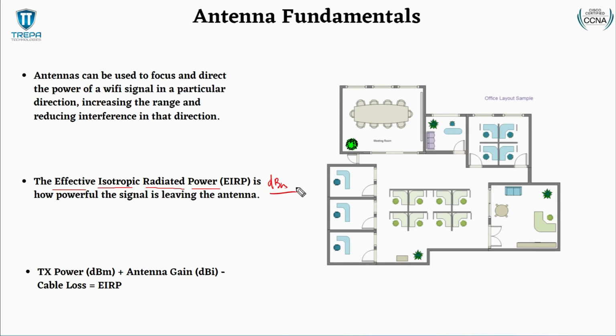So every antenna has a different EIRP rating. And what that means is, like in America, the FCC says 36 dBm is the total strength you can do for Wi-Fi. You can't go stronger than 36 dBm. So antennas will have an EIRP rating saying, okay, this antenna can do up to 50 decibels, or this antenna can only do up to 20 decibels. And then if it's directional, unidirectional or omnidirectional, that's also going to change how the antenna manufacturers put out its EIRP.